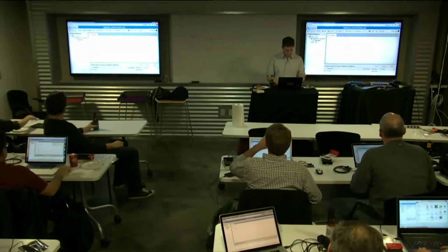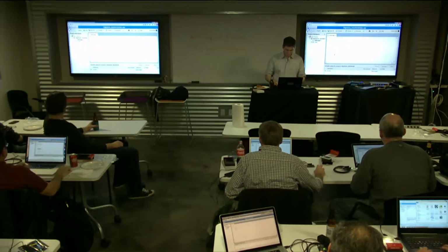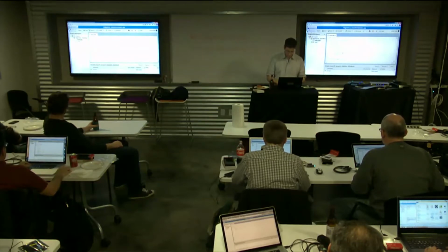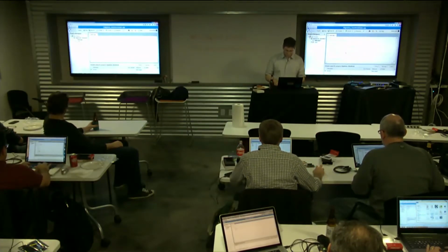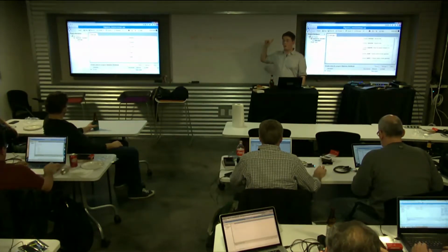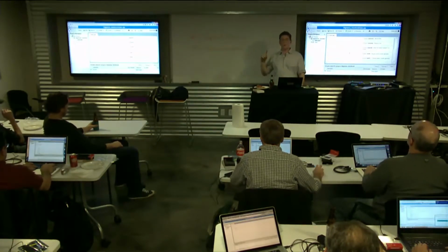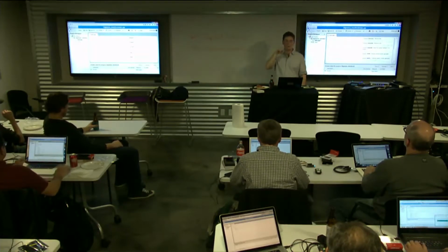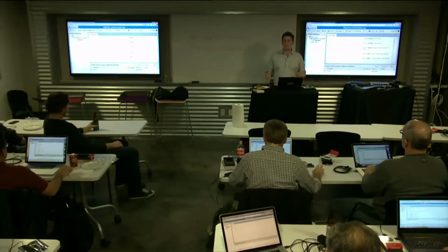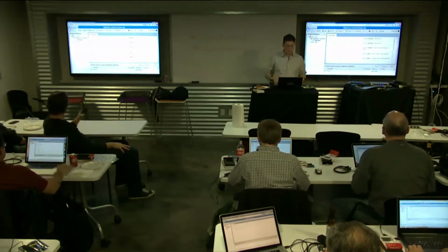So I'm going to add a thing right here that says LED off, and a thing right here that says LED on. Now what you'll notice is two things. One, I'm saying the LED is off when I send a 1 value. If you've been eavesdropping, you would have heard that the LED here is a negative logic LED, meaning 1 turns it off, 0 turns it on, because there's a little inverter gate in front of it. The manufacturer decided to use that part, probably because it's cheaper than a positive logic LED. So just keep in mind, 1 is off, 0 is on for this magical LED.